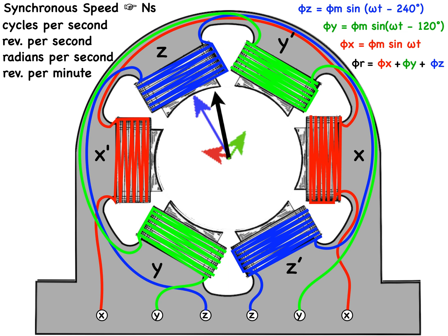It can be converted from cycles per second to radians per second. When comparing synchronous speed to the rotor speed, since rotor speed is usually in revolutions per minute or RPM, so should the designation of the synchronous speed. However, when comparing the synchronous speed of the frequency to the frequency of the supply, we're talking about cycles per second or radians per second. So you have to be aware and consistent when choosing and working with the designation.